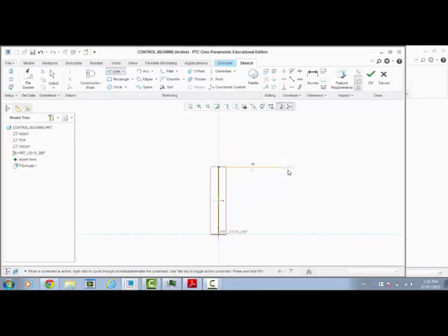I have to watch out because the very small green L's for both lines come up, and what that says is that both lines are exactly the same length. If we want them to be the same length, that's fine, we can click at that. But if you keep that and try to change it, it's going to change the 41.5 height as well at the same time. So you have to be careful. We will just continue on freehand sketching what we think this object will look like.